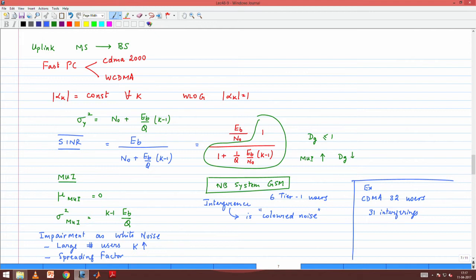It transmits control information, it transmits a pilot channel, it transmits, at the end of the day, anything that is not my user signal. The pilot channel is actually useful for me. I use it to do channel estimation, but when I want to detect my user signal, what happens? It is actually interference to me. So, in the downlink, you have to keep in mind that it is 31 plus other channels. Whatever the base station is transmitting is going to cause interference to me. In addition, other base stations transmitting are also going to cause interference to me. So, in a CDMA system, the role of interference is something that we really have to get our hands on.